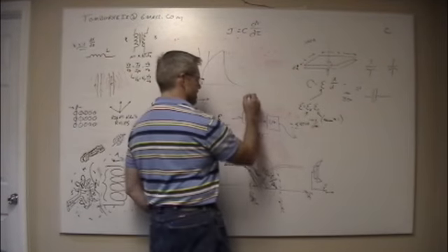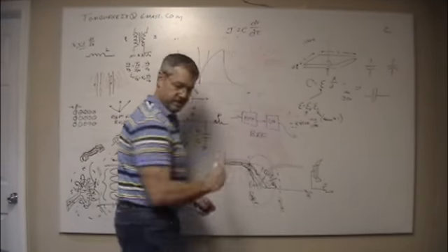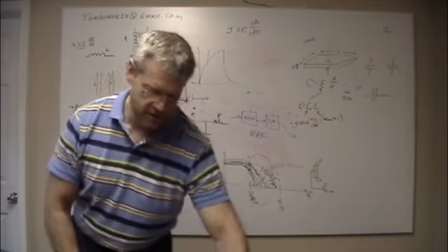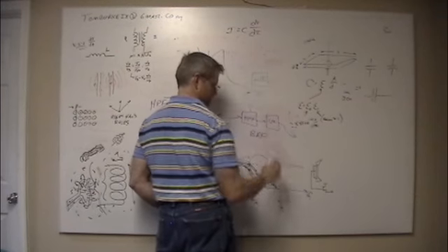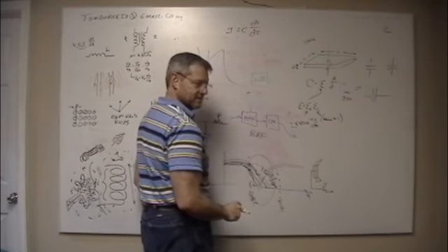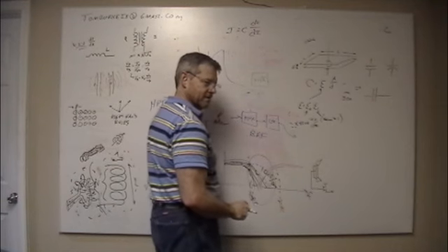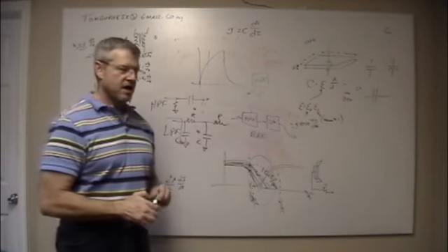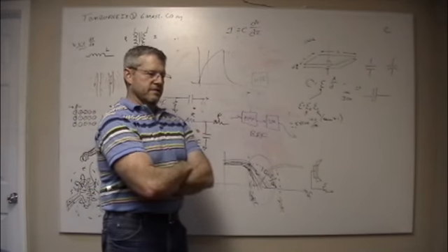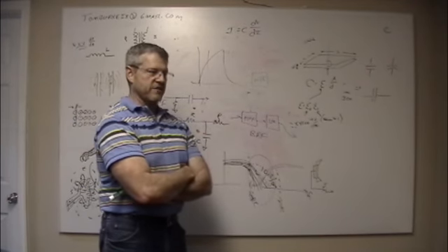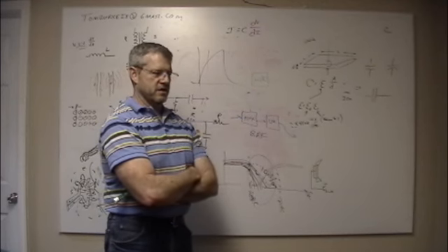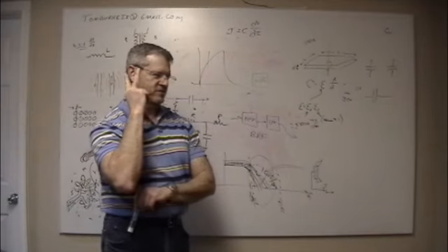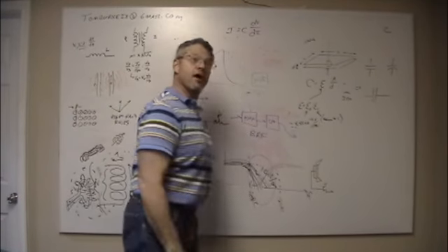And if I put a high pass filter in parallel, let's see, let's use a different color. What I got here, green. So essentially, the bandpass is basically giving me a very close, narrow scope to chop out. Yeah, it's a notch. It's also called a notch filter. I think in terms of audio, it's like remove this frequency. It's a notch filter, and I like to talk about it as tuning in the dad notch. Talking to your kids and they tune it right in and they can't hear a damn thing you say until you say the word money or something like that, and then it goes away and they're like, what?